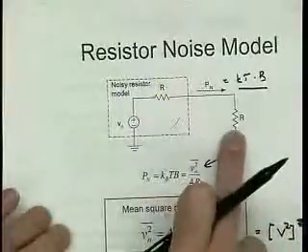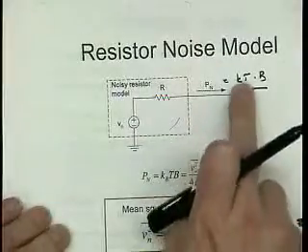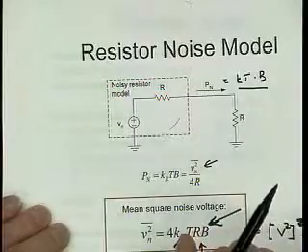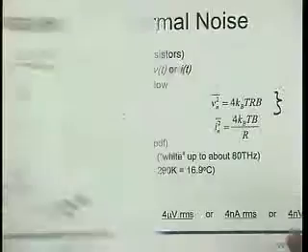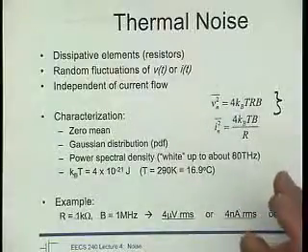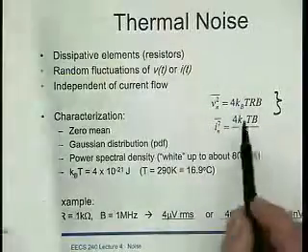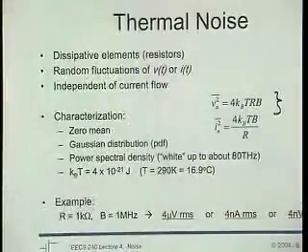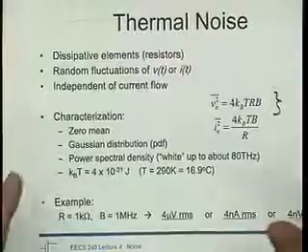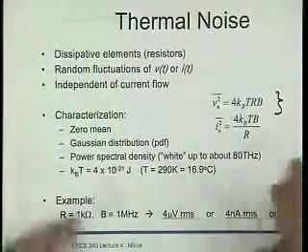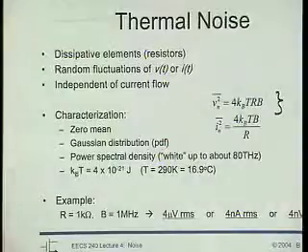It's really power that is delivered to the load, and the amount of power is kT times B. But it is more convenient to actually work with these units of volt squared, and we can always convert to the power simply by dividing by the value of the resistor R. Then we would get the power. But afterwards, when we do noise calculations, this formulation is more convenient. So we refer to this and say it's power, but it's actually got units of volt squared.